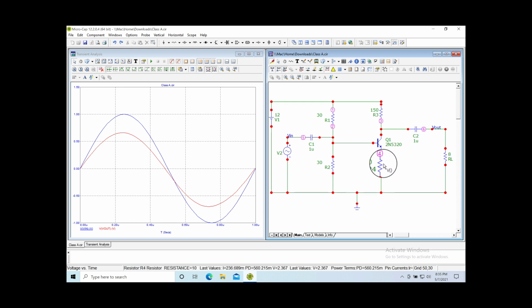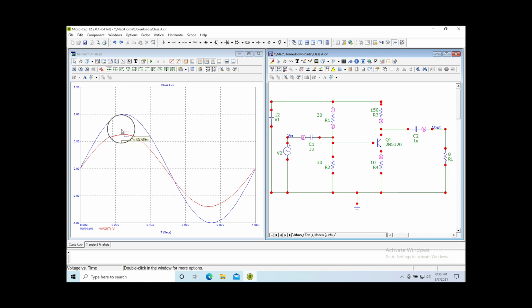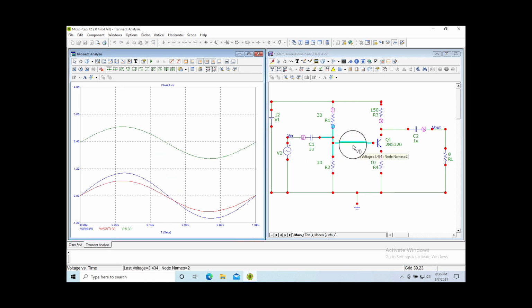So you're putting a lot of current in this, and that means this transistor has to be on pretty hard. That might make you think about these signals over here. See how they're in phase? Well, that's because, here, let's come over here and look at the emitter. Should be just 0.7 volts different, right? Let's turn off these two guys.